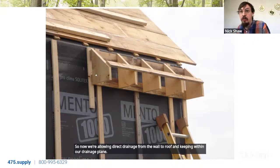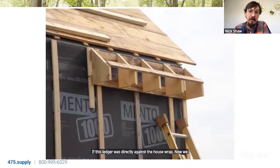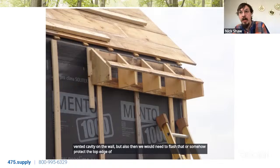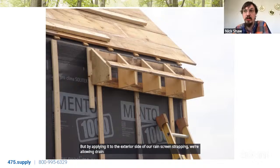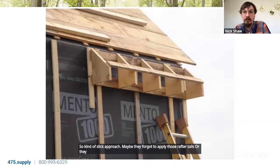If this ledger was directly against the house wrap, now we're interrupting that vented cavity on the wall, but also then we would need to flash that or somehow protect the top edge of that ledger framing. But by applying it to the exterior side of our rain screen strapping, we're allowing drainage and venting at this location. So kind of slick approach. Maybe they forgot to apply those rafter tails, or they thought this is an easier approach. I'm typically seeing this with Simpson hardware to support those eaves and overhangs.